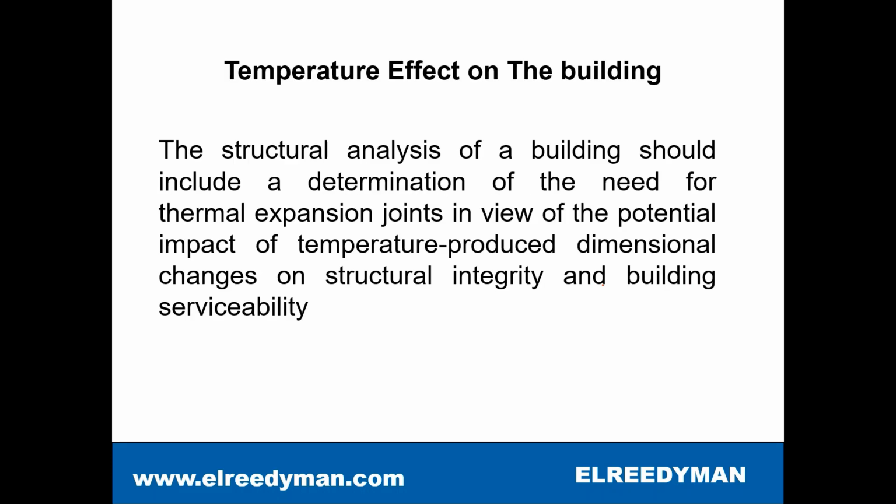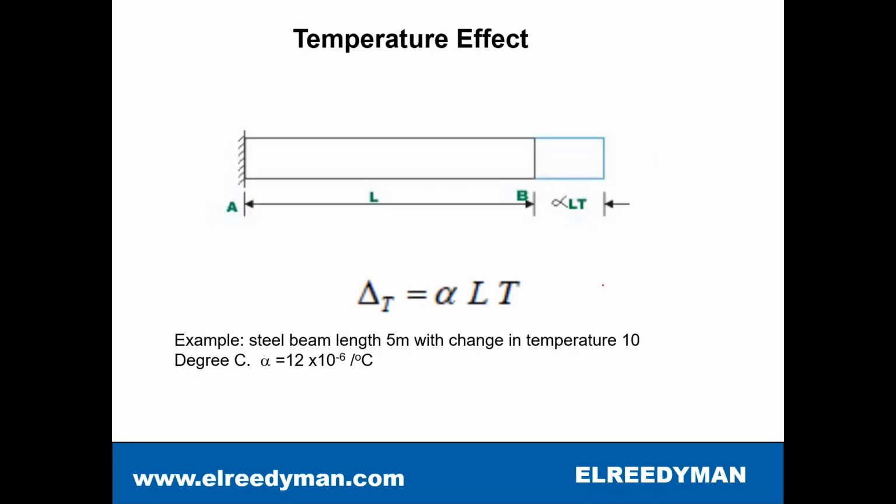Fatigue property, fatigue. Another topic that we need to discuss here is thermal stresses, the temperature effect on the building or structure itself. The structural analysis of the building should include a determination of the need for thermal expansion joints in view of the potential impact of temperature-produced dimensional change on structural integrity and building serviceability, as some deformation or cracks can happen due to thermal effect or temperature effect.